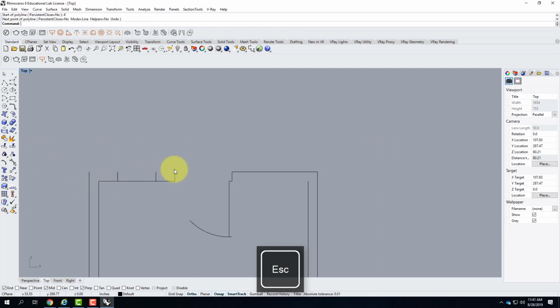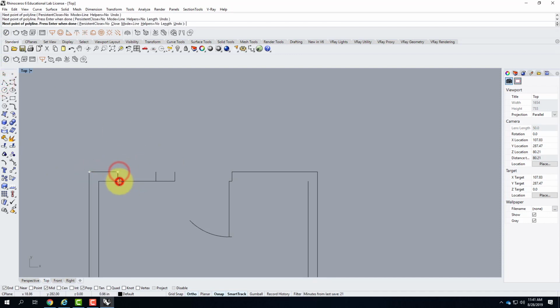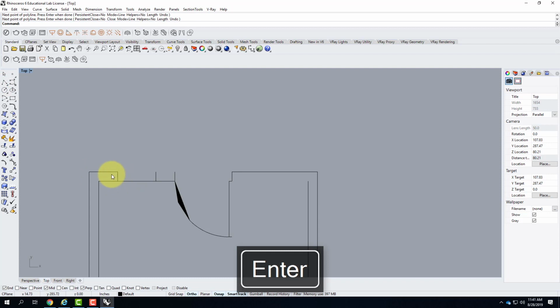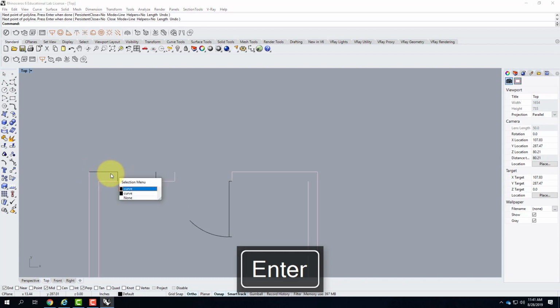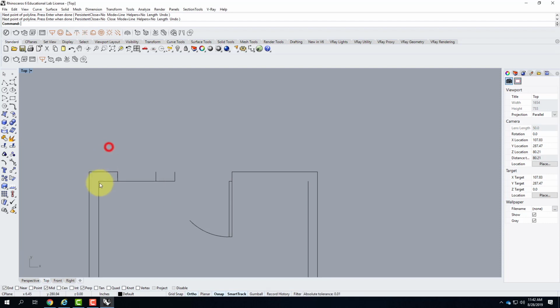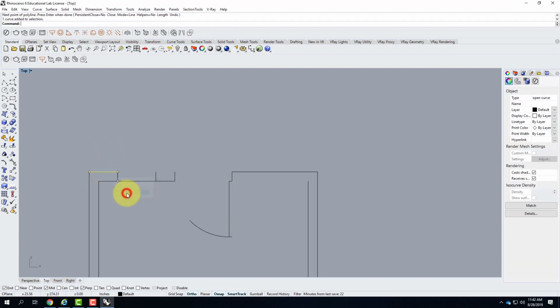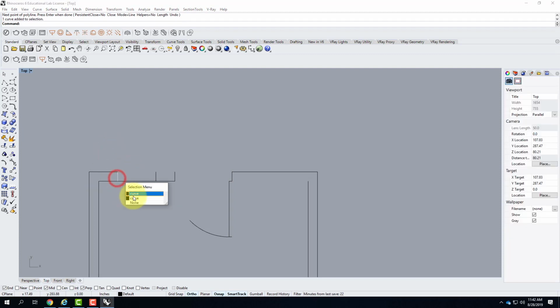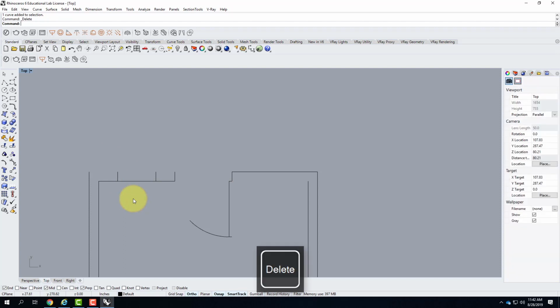As soon as I go to extrude this shape into 3 dimensions, I get duplicate surfaces on top of each other. Those duplicate surfaces will then have conflicting materials. The renders won't turn out. It's a really bad thing long term. So we want to make sure we're being nice and clean in our drawings. So let me get rid of that duplicate line there that I don't need.